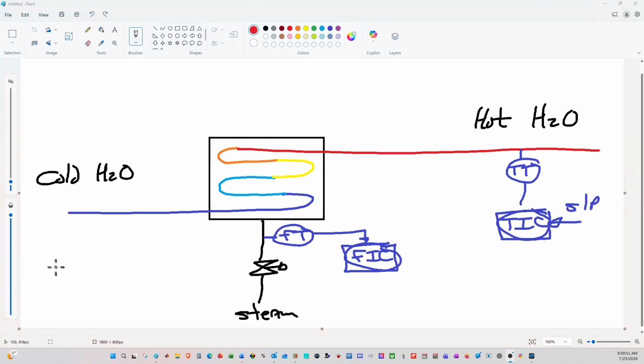Now imagine the feed forward part of this loop. Feed forward is where we pick up a disturbance before the process is affected, and hopefully we can take the correct action from that. We could either have a change in the flow coming in, or a change in the temperature, and that would be information we can collect, and that would form part of my feed forward controller.